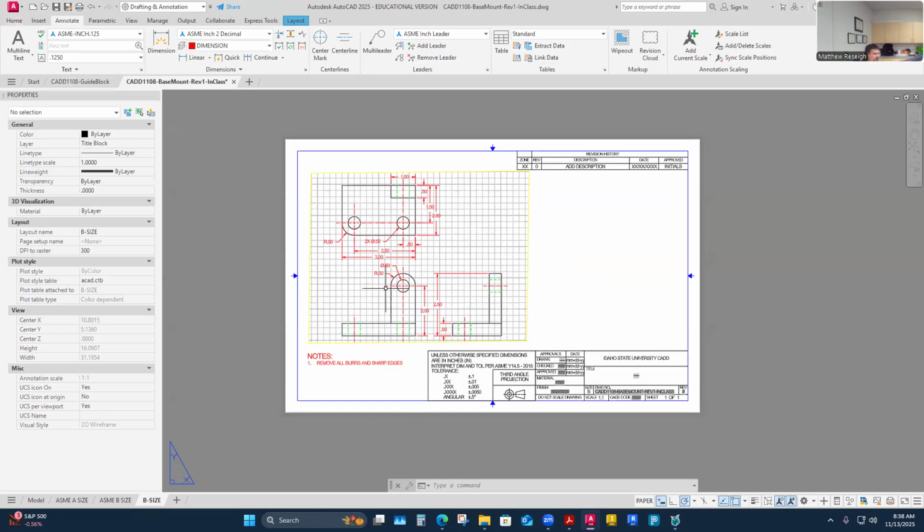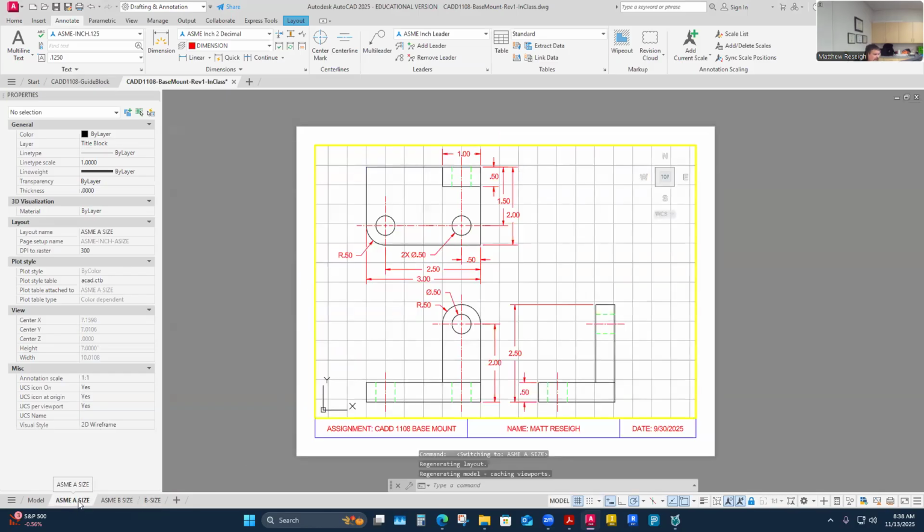I think it's probably going to be just the order that it was in the list. Maybe I would have wanted A size to be first, or usually you have a running order list that is really specific. Once you build a print packet in its order, there is a flow to it. When you're creating a set of prints, you're generally showing assemblies, then breaking down into parts, and then part details, and maybe cut files. So generally, for every company, there's a flow that they want with their print packs. You wouldn't want them all mixed up, so you'd want to be able to control that.